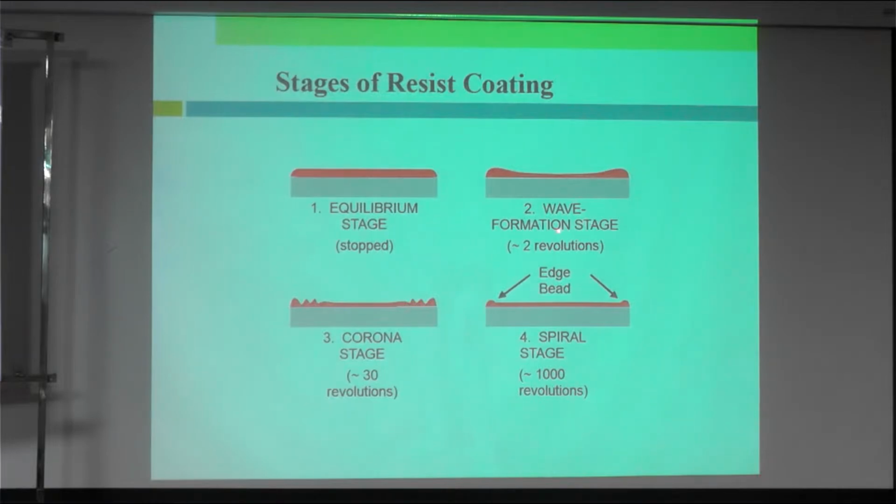With a little bit higher revolution, you have this kind of thickness developed. Then if you want to remove this, you have to have a higher speed of RPM for the spin coating. So this is what happens. And if you don't go through the stages accordingly, the thickness of the spin coated film might not be as intended.